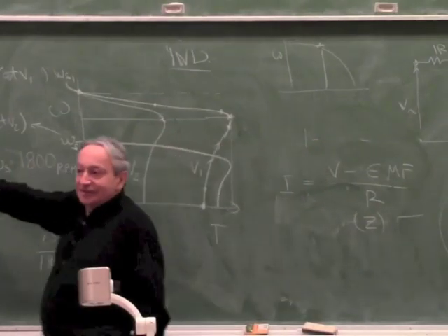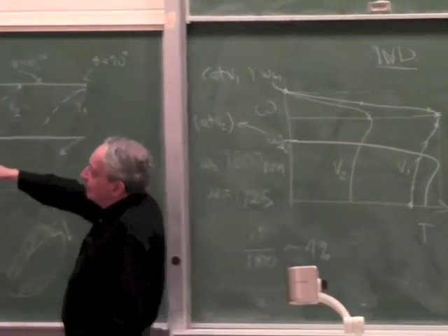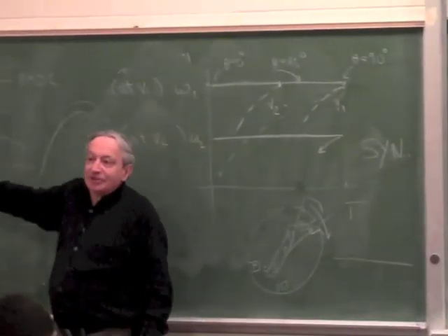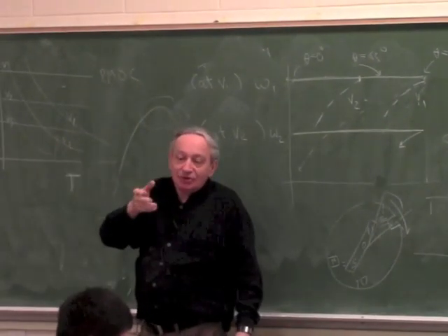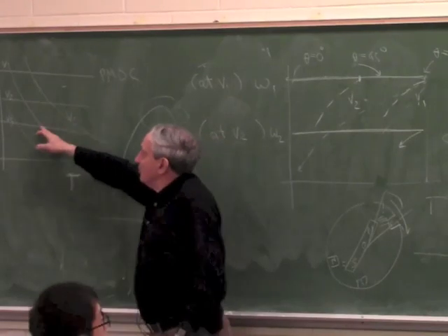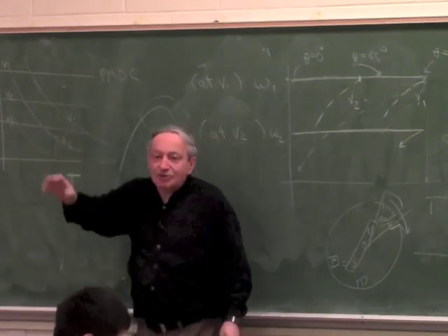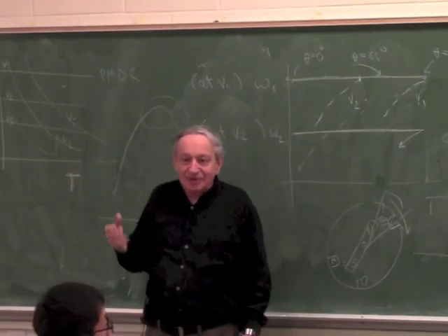Same as here. So you see what's more confusing here, because on a DC motor, there was only one parameter in control, voltage. That's it. Because even the torque I can adjust with voltage. If I want at some point more torque, I just can increase the voltage, the motor will give you more torque for that load. So it's really 1 degree of freedom, okay?